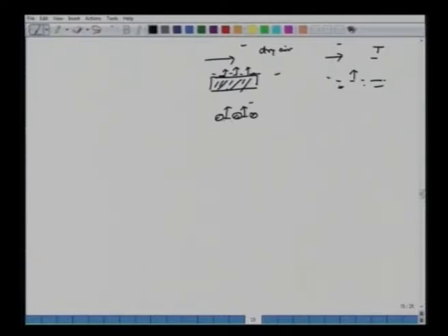But why do we see a decrease here, a falling rate? Because we are expressing our rate based on the total area. Had we expressed it based on the wet area, then of course this would have been the same here. Since we use the total area, the rate decreases because moisture evaporates only from the wet patches.